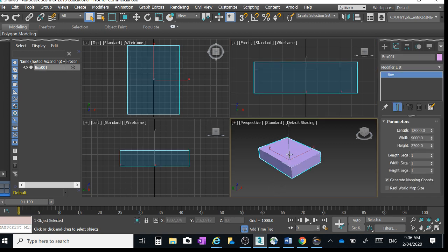Next thing we need to do is to hollow out the inside of the block to make it so that we've got some wall thickness around the outside walls of the building. There's a number of ways that we can do that. The easiest way would be to clone that box and rescale it slightly. Now we'll work on the theory that the walls are 120, we'll call it 110 millimetres thick. Actually we'll make it 120. So what that means is that we've got 90 millimetre framing, we've got a layer of plaster on the inside that's 10 millimetres, that takes it up to 100.